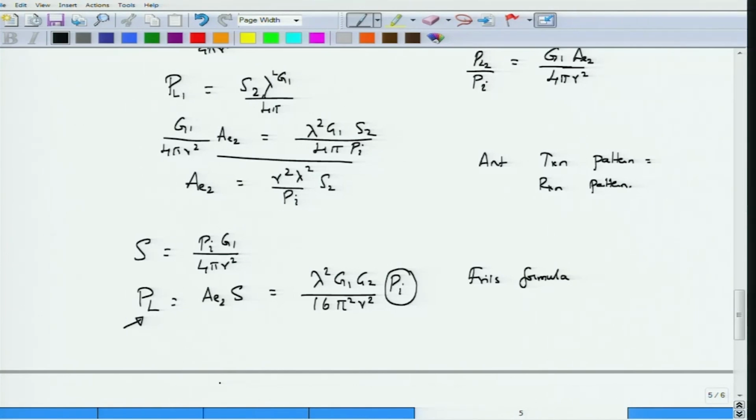This is actually used in estimating the range of power that is getting lost. In fact, this kind of formula or the modified types of these formulas are used to estimate the path loss from one transmitter antenna to the receiver antenna. If the power obtained is PL and the incident power is Pi, the reduction from Pi to PL and the range over which this reduction happens, both can be calculated by the Friis formula. For example, the gain of a half wave dipole would turn out to be 1.64.